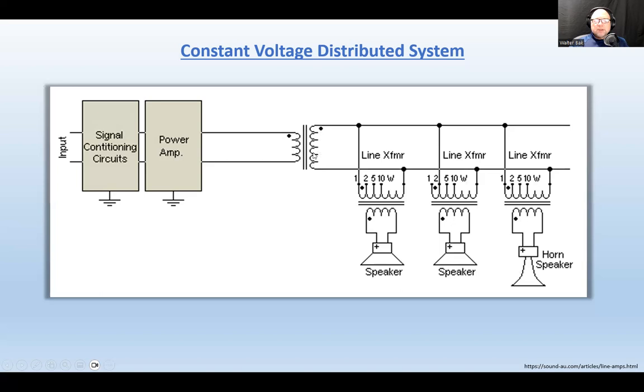However, if the secondary windings of the transformer are half as much, say this one has 1,000 windings and this one has 500 windings, so this is a 2-to-1 ratio, then if we have 100 volts here, it's going to be 50 volts here. But in order to keep the power, because power goes through untouched, then of course the current has to be larger. Right? So that's just the basics of transformers.